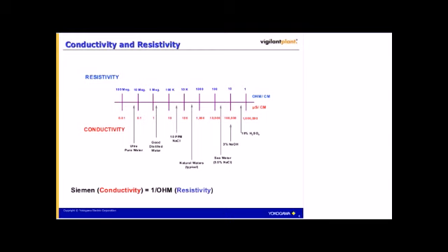It's the same thing. From the example shown on the scale, we can see that conductivity ranges from very low values, theoretically pure water around 0.055, 0.057 microsiemens, to very high values, which are several 100,000 microsiemens for acids and caustics, as the concentration of the conductive ions increases. Remember, the amount of ions present in the liquid relates to the level of conductivity measured.